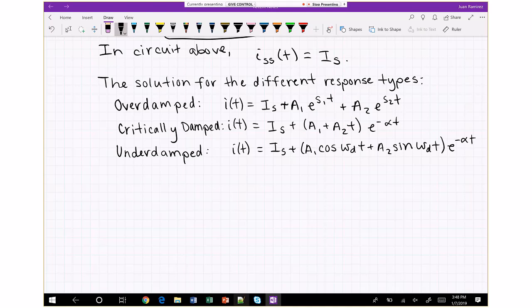So we assume time has gone by, and actually we would look at the circuit right after the transition, because we want to consider the inductor as an inductor and the capacitor as a capacitor, not a short circuit for the inductor or open circuit for the capacitor.